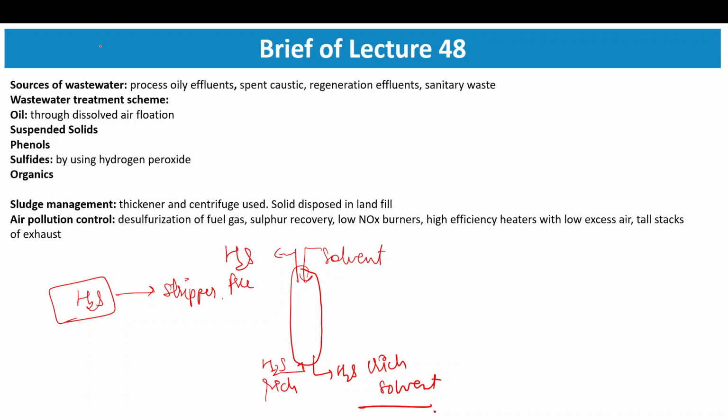Then there are a number of organic products which are formed. Each of these steps will generate oily effluents, right? Further, as I mentioned, caustic can also be used to remove H2S, or water can be used. So spent caustic. Further, in the fluidized catalytic cracking, you use catalyst.